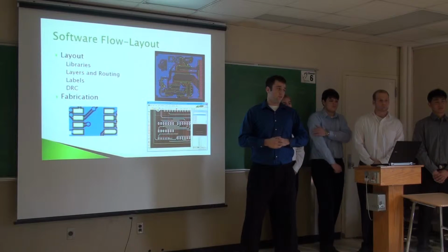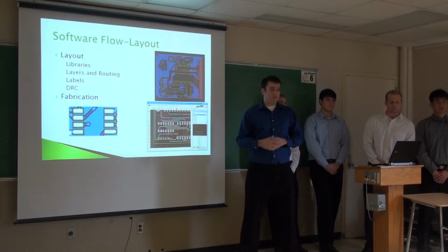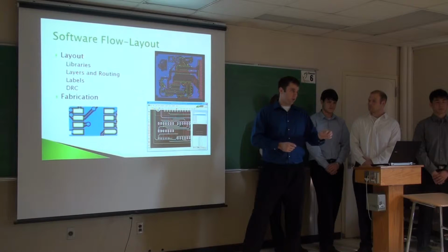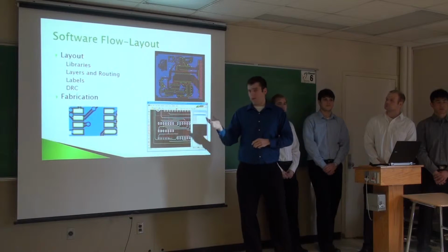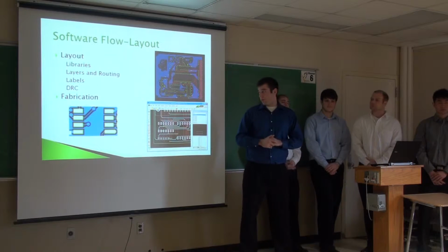This is very important because when you get your PCB back from fabrication, you actually need to know where all the components go. It's very hard to just look at it and know which capacitor goes here, which battery capacitor goes here. So you can actually add labels that will print on the solder mask of the PCB board.